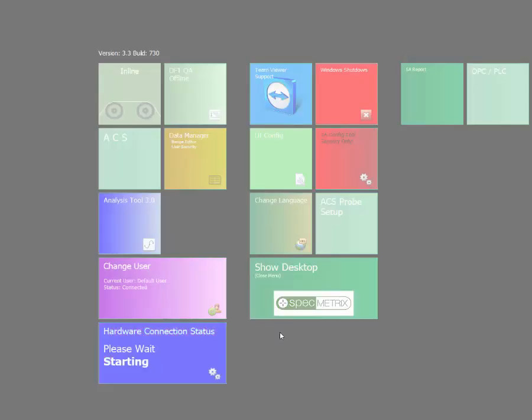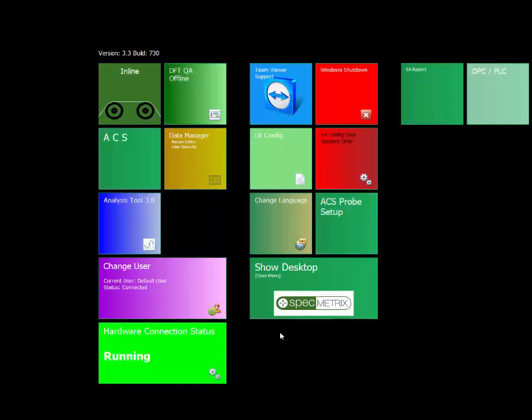It is a point to note that with the new software version, anytime the system is getting the hardware initialized for traversing systems, it will execute a homing routine, which will move both probes, or all the probes attached, all the way to their home to torque position and then back out to their zero position, so that they are confirmed, ready with distance and measurement, and can move from there.